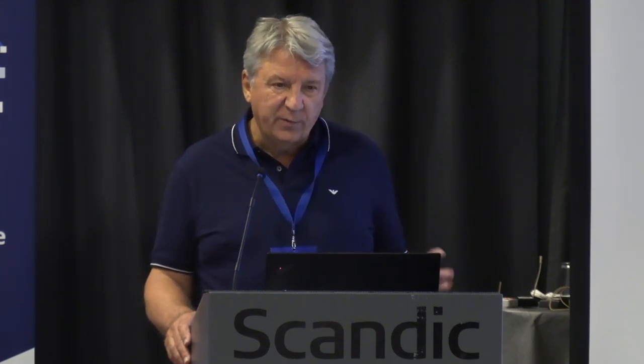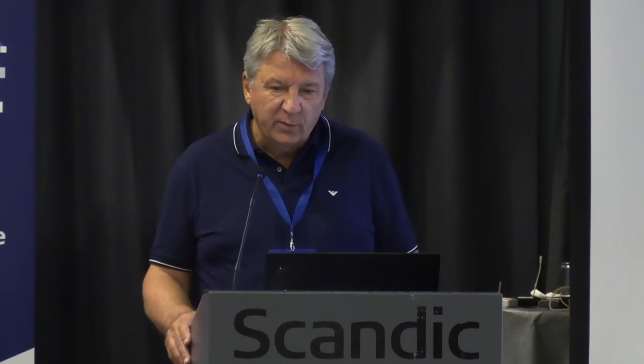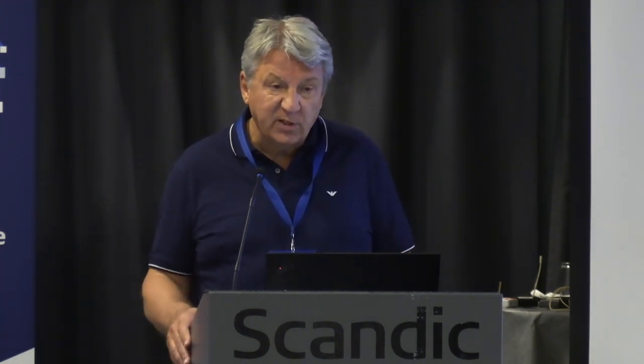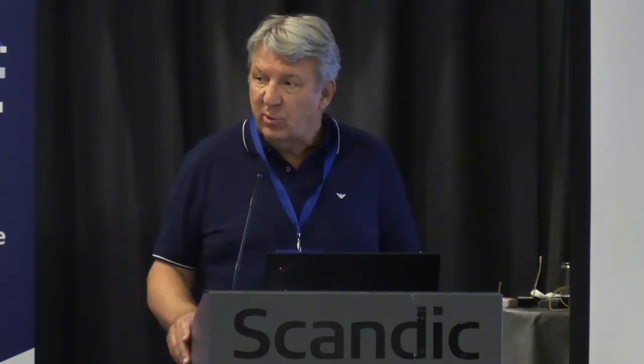in the last 10 years, we also bring together satellite-derived bathymetry, because we still have a lot of areas, especially coastal transition areas, where we do not have a lot of detailed surveys. And then we are using the Sentinel data to derive by a 10 by 10 grid also the bathymetry. And that works in a lot of the European waters because they are transparent enough, and it can work up to, say, 15-meter depth. And also we use LiDAR data because there is some LiDAR on the coastal zone.